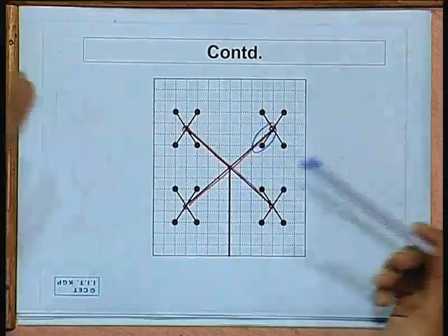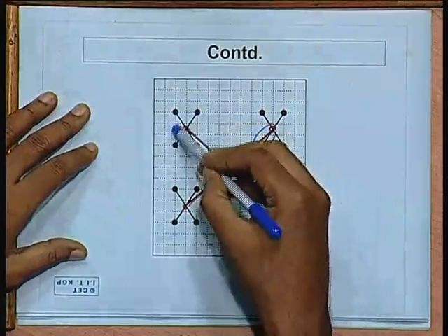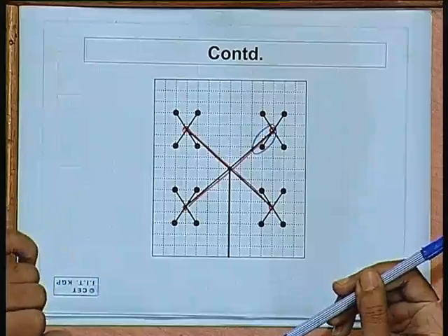Okay. So, this H and X are very similar in terms of the layout, but only the wires here are running in a non-rectilinear fashion. They are running at angles of 45 and 135 degrees. Okay. Fine. Here also we have a single layer for the clock. Single layer for the clock, yes. Normally, all the clock routing algorithms route the clock on a single layer.